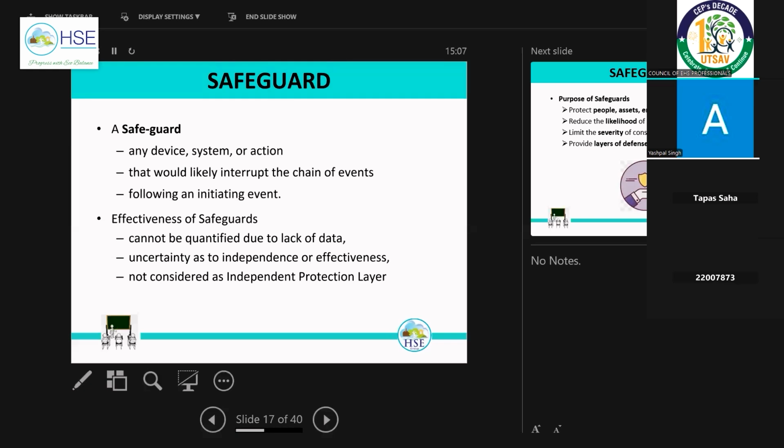So normally there is a range for each gas detector that covers the range. Say, for example, our gas detector covers 5 meters, and we install a total of four fire and gas detectors in four corners. So our area is, say, 50 square meters or 100 square meters. In that case, this 5 meter diameter gas detector will not cover all the areas. So the best way to ensure the coverage is to do the fire and gas mapping study.